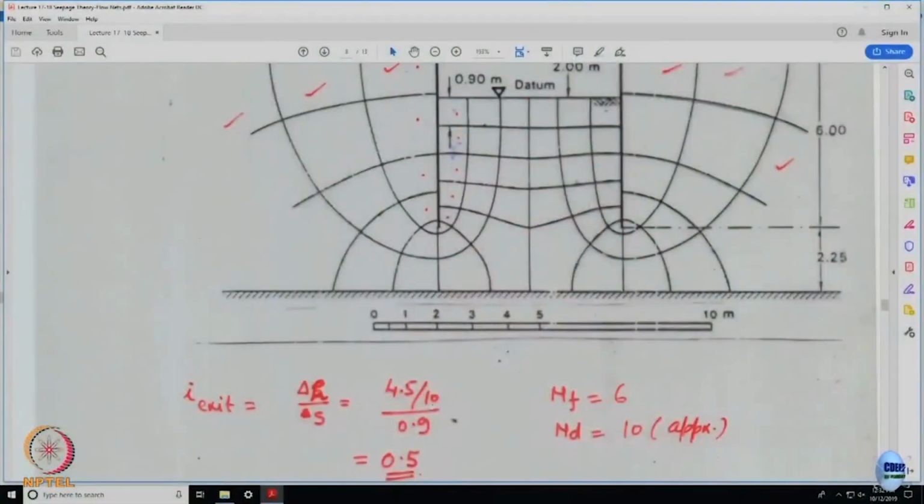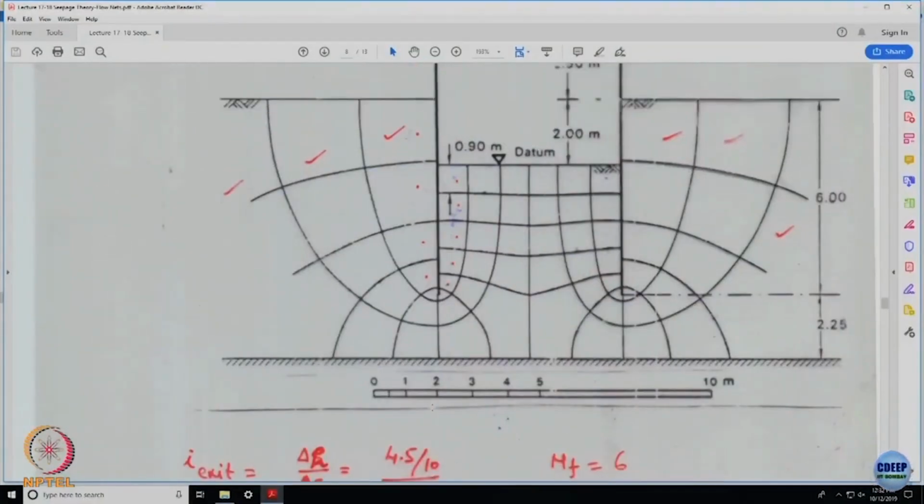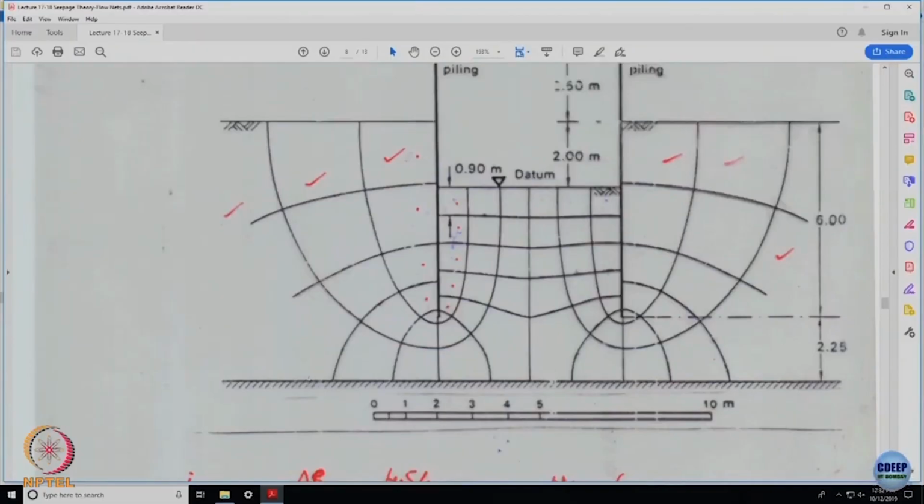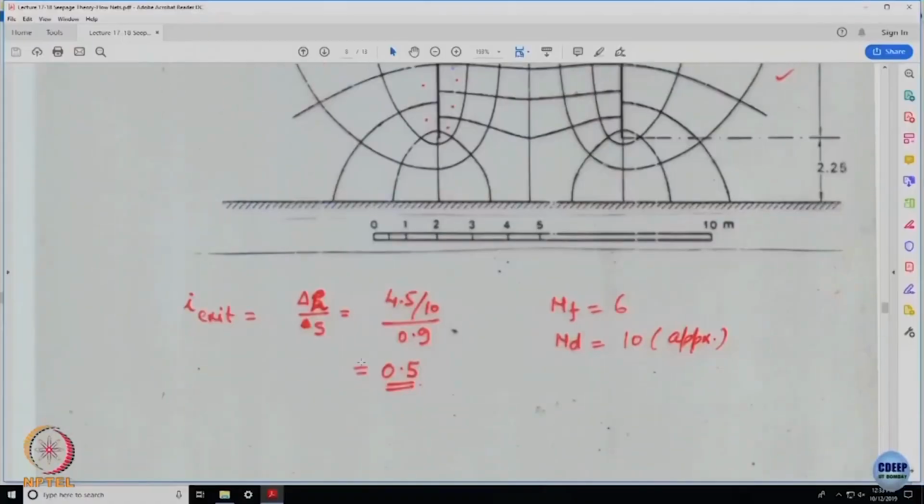The question which you asked about the symmetry, I hope you can realize here what is contributing to the total discharge. We talked about only one half, channels 1, 2, 3 and a fraction, and this other portion is also connected with the channels 1, 2, 3. So, it is about 6 or 7 which you might consider, and then the number of flow channels contributing to the system would be 6 or 7 and the drops would be 10, and then you can solve this.